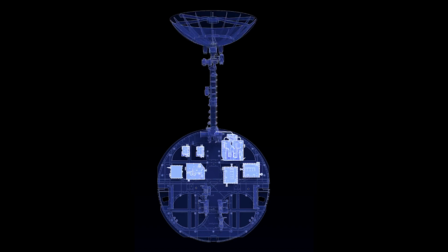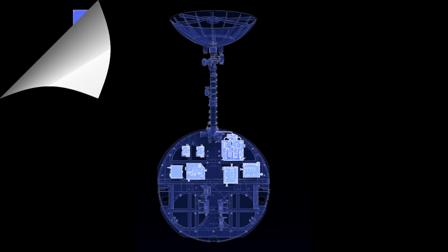The RF, radio frequency, communications electronics are located underneath the spacecraft bus on the communications panel. The Ka band transmitter is responsible for ingesting the high-speed science data from the science data recorder (SDR) and prepares the data for downlink to the ground station. The traveling wave tube amplifier provides very high output power for transmission to the ground through the high gain antenna. The science downlink can accommodate data rates up to 500 megabits per second.